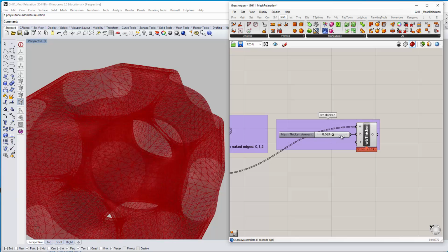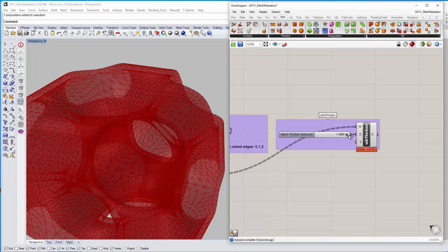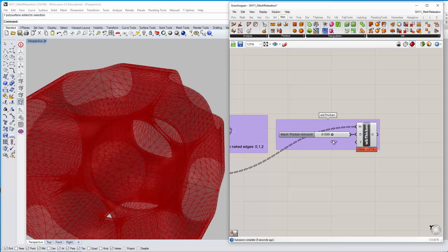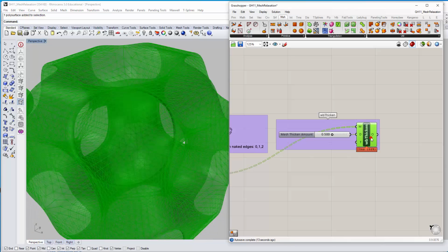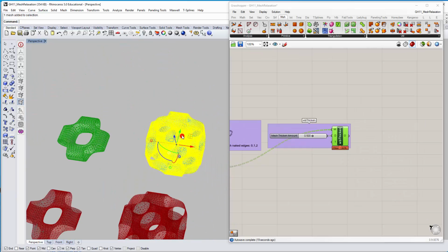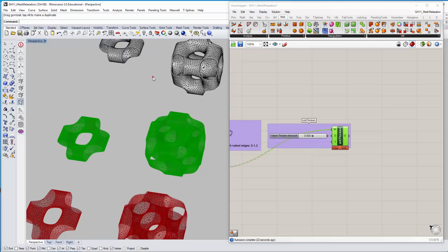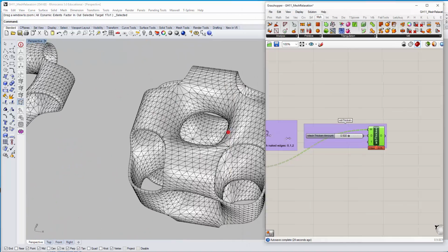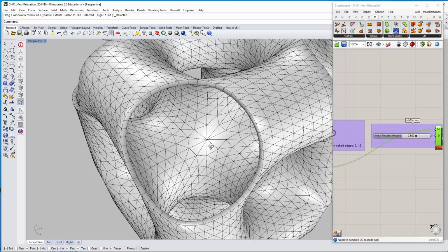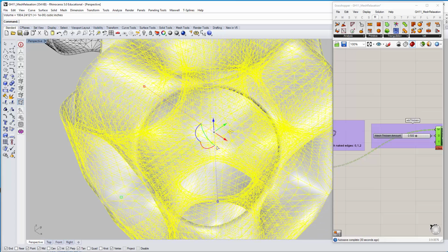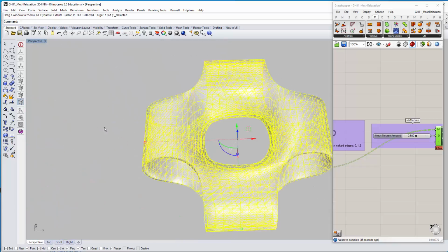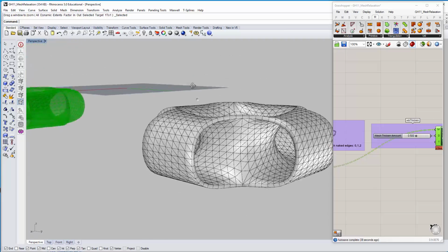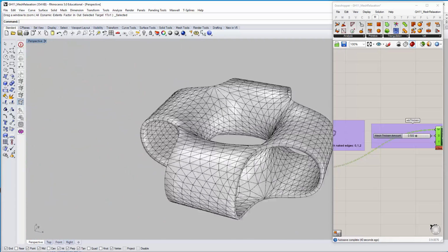As you can see, it's really easy to modify because these are all mesh triangles, and it's a lot lighter than the equivalent offset of it in NURBS, Rhino NURBS surfaces. So bake it. Let's see. And these are absolutely watertight, fit for 3D printing, full meshes with offset thickness that you can specify.